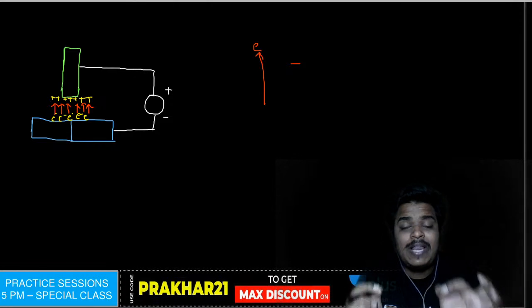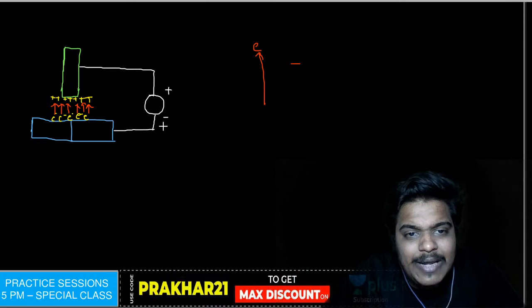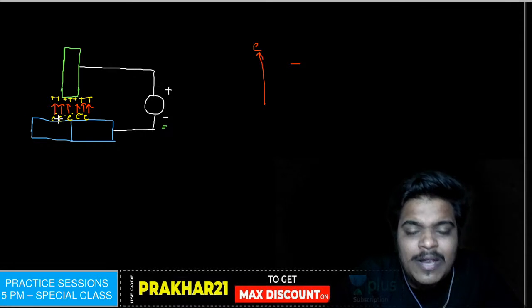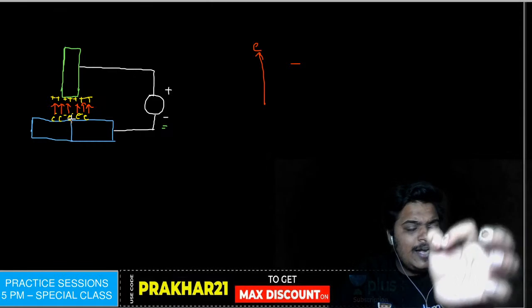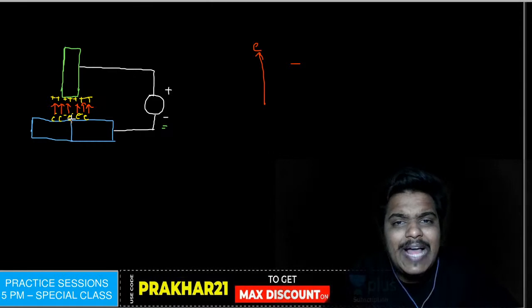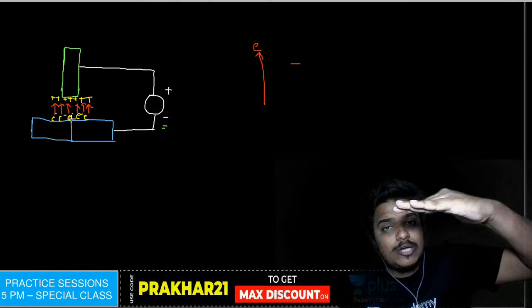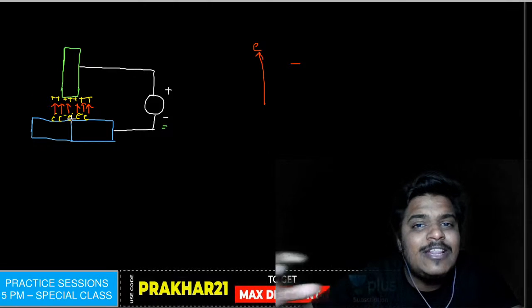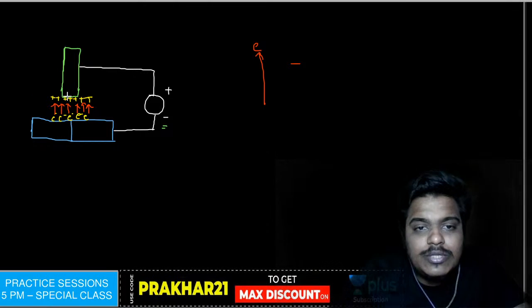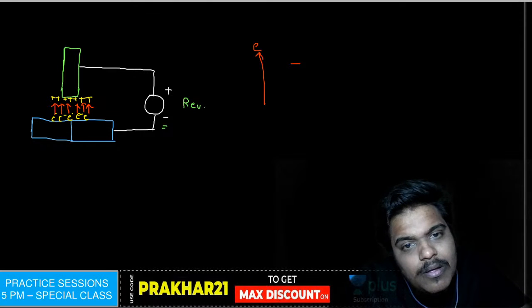That is, electrons will now try to jump from the workpiece to the electrode. Why? Because the negative terminal is attached to the workpiece. So the electrons will be gathered on the border of the workpiece. And now, if they are gathered on the border of the workpiece and a positive force is trying to pull them up, that is why they will move in the upward direction, breaking the film of Al2O3. Yes or no? So when the polarity is changed, this is known as reverse polarity.